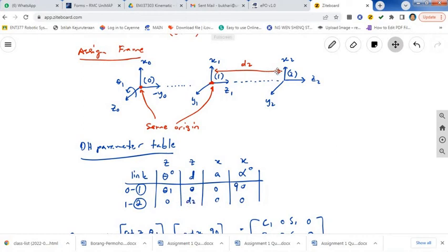Your arm can extend and retract. D is variable, maybe 1 centimeter, maybe 100 centimeters, depending on the information from the sensor. Theta also comes from the encoder. The 90 degrees comes from your robot design, so you design your robot, and the position changes 90 degrees.